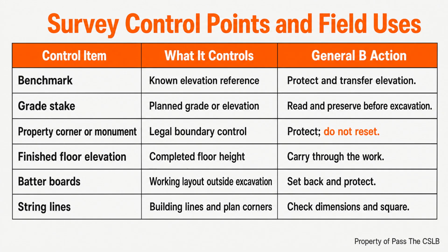After pre-marking, the contractor contacts the regional notification center at least 2 working days, but not more than 14 calendar days before excavation. The day of notification does not count as one of the working days. Weekends and state holidays do not count as working days. Here is the common scheduling trap.